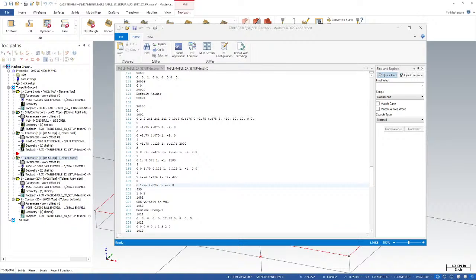So a tool plane based toolpath is either 3-axis only, or it's a 4-axis operation, or it's 3+2. So you can have a 5-axis part that is entirely done in 3+2. I do it all the time. There's no live 5-axis cutting that's required. Sometimes you can add it if it saves time, right?